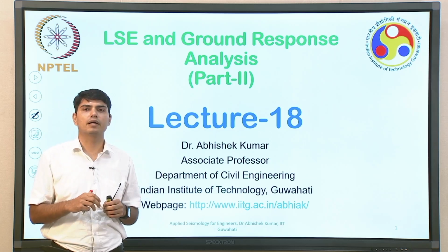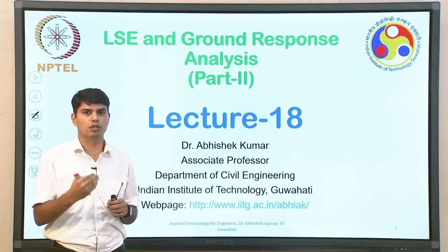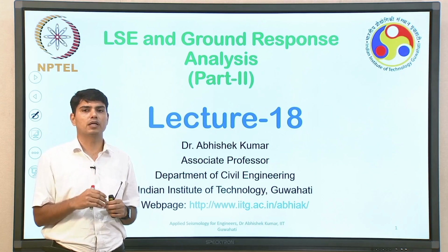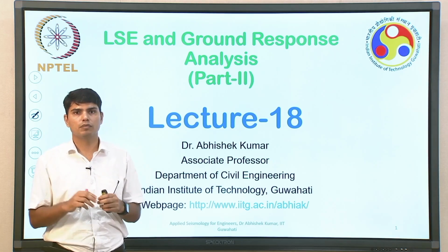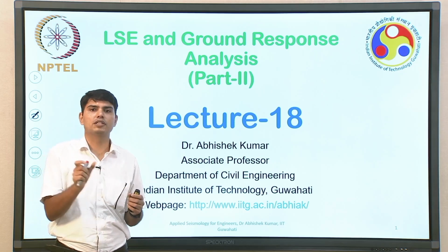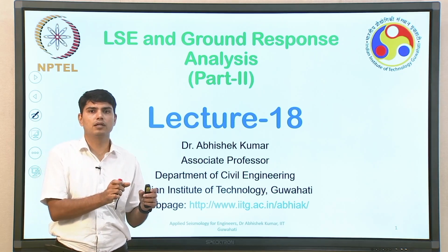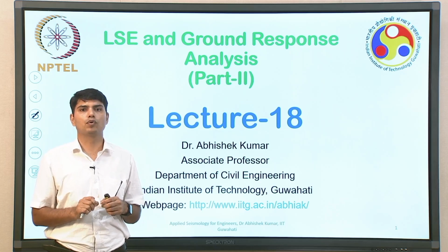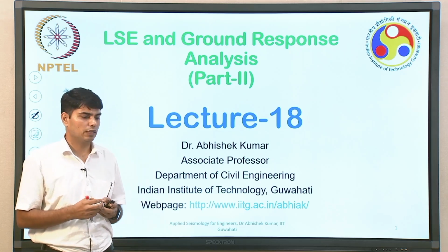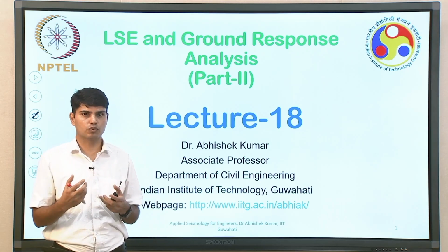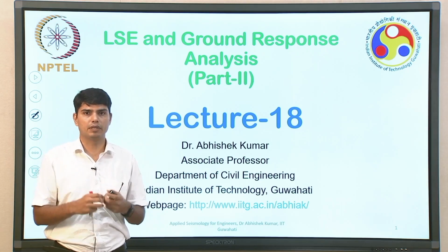remember that at the time of developing the solution for one dimensional ground response analysis, that too based on linear approach, we have to have one is transfer function, second is Fourier spectra of input motion. So, Fourier spectra of input motion means whenever a motion is given to you, generally because of earthquake motion, it will be random in nature.